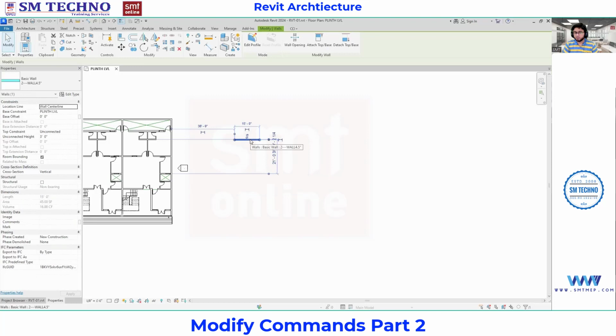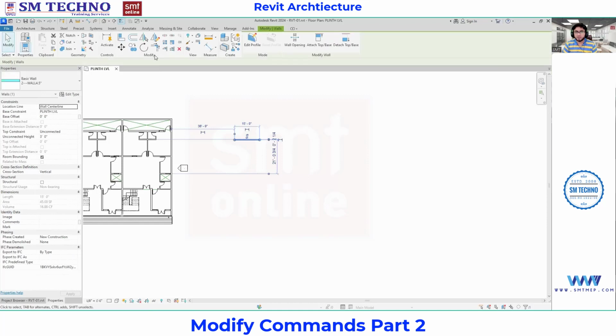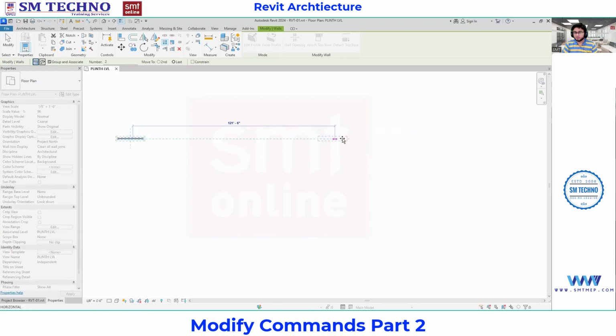So if you are going with the next option, when you select the array, here we have the last. Last means from the center of this object. I have selected this object, and here I am going with the array option. If you are going with the last option in the linear, select the point from here, and what is the last interval you want? Something like 135 feet, for example.